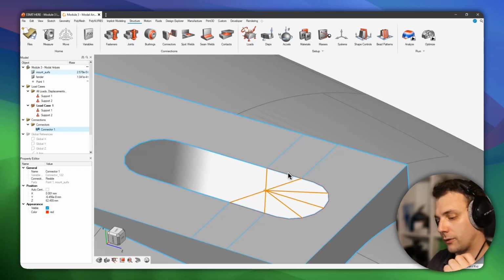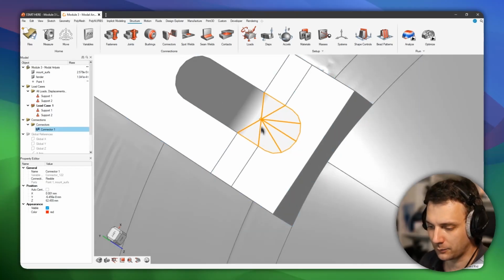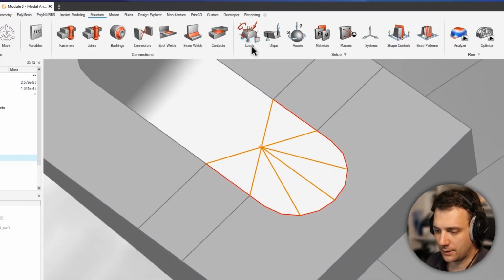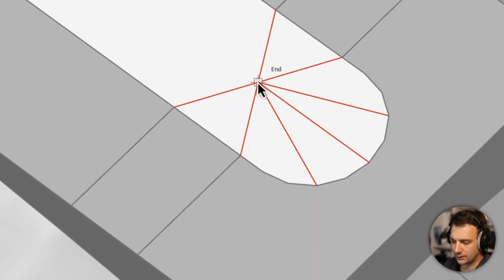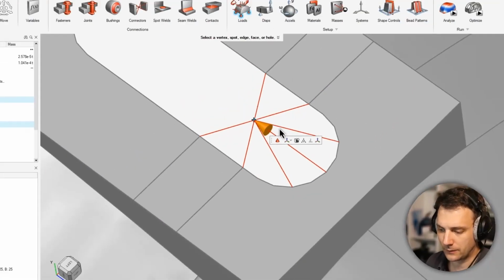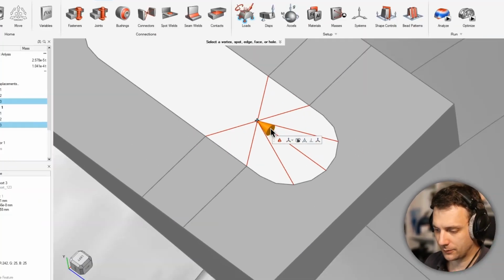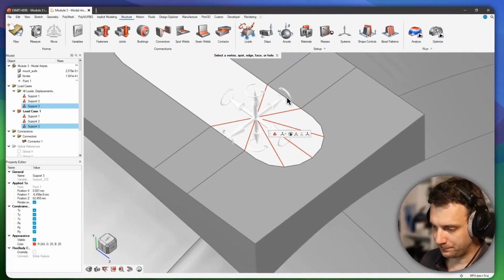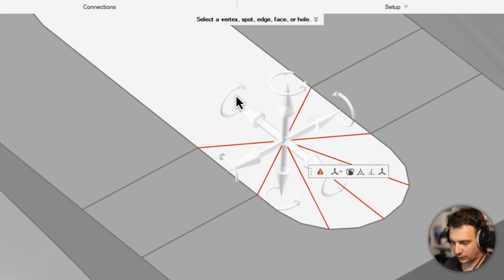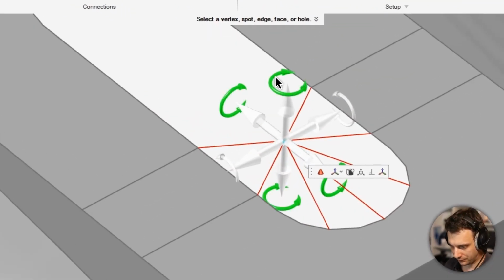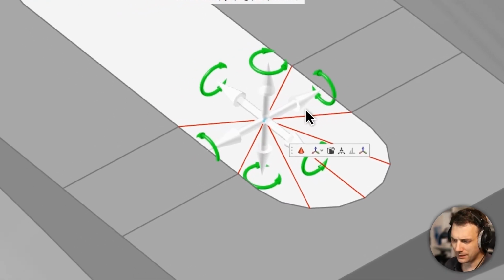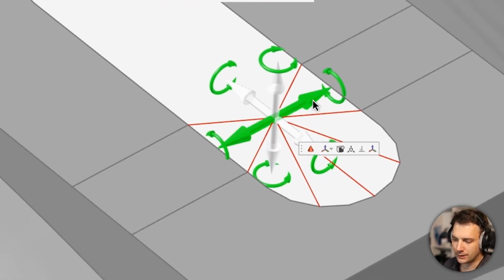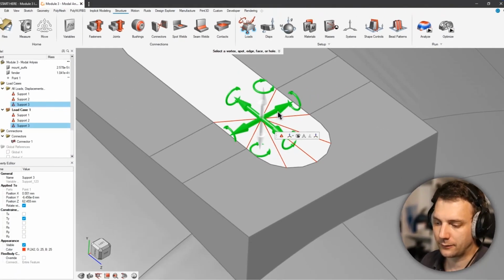So flexible is the way to go. Okay, so we have a flexible connector here, and then we can constrain the point here. That's the master node. And for sure we have to also let the rotations happen here. But additionally to the rotations, we would also like to have this thing happen.